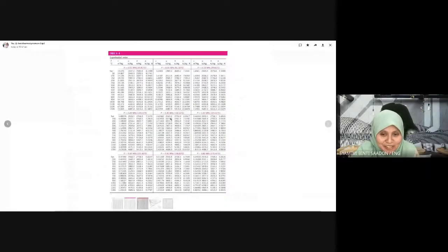You start at the table, with the table for 0.3 megapascal. Okay. So this one, 2865. If we extrapolate the table, maybe we get the temperature 198 degrees or 195 degrees. But it's okay here. We just take the nearest possible value. 2865 is close to 2865.9, so it equals 200 degrees Celsius. So that is the answer for T2, T final.